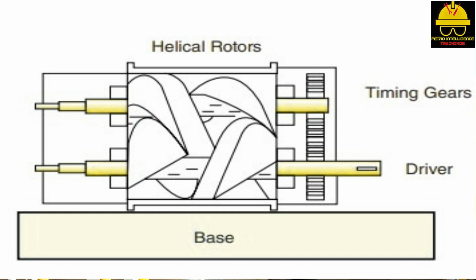Rotary screw compressors are designed with an inlet suction line and an outlet discharge port. The 2 rotors are attached to a drive shaft, timing gears, and a driver that provides the energy to operate. Flow enters the device and is moved axially toward the discharge port. The majority of compression takes place very close to the compressor outlet.